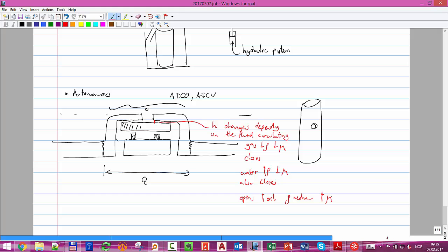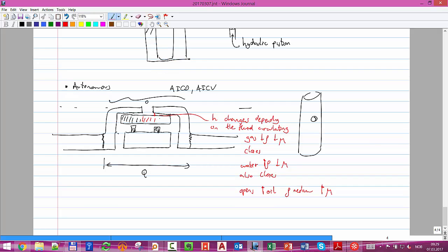Yeah, so that's that effect. You also have it in the valves of the reciprocating pumps. It's called clinging effect, and that device uses something like that. It uses that effect, so that moving part sticks to the top, reducing the opening, thus choking the flow. Clinging effect.